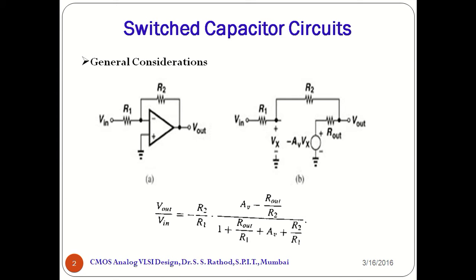In order to understand the motivation for sampled data circuits, let us first consider a simple continuous time amplifier as shown in figure A. This is used extensively with bipolar op-amps. This circuit presents a difficult issue if implemented in CMOS technology. Recall that to achieve a high voltage gain, the open loop output resistance of CMOS op-amps is maximized. Typically, it approaches hundreds of kilo ohms. We therefore suspect that R2, the feedback resistor, heavily drops the open loop gain. Thus, it degrades the precision of the circuit.